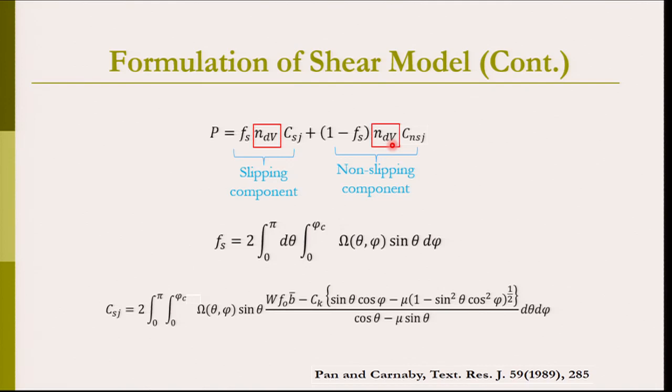In a similar fashion, one can also calculate the geometrical properties. For example, the pore size distribution. We have calculated in the past, depending upon the number of fiber to fiber contacts in mesodomain dV, we can calculate how many contacts are taking place, and on the basis of those contacts one can define the polygonal geometry formed by means of fibers, and one can calculate the pore size distribution for such materials.